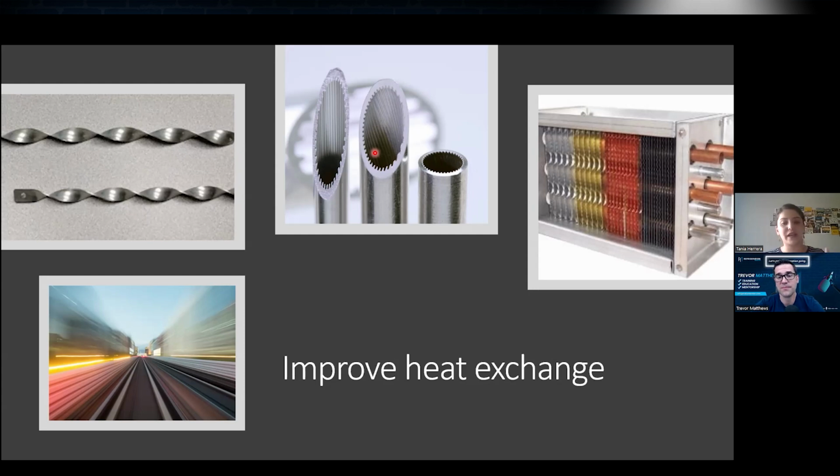For instance, in a condenser, these are very commonly used because in a condenser the inlet is gas and the outlet is liquid, right? But in the middle, we have a mixture of that. So we want the liquid to be flowing through all these mini channels, and the gas flowing through the inside of the piping helps us to have good velocities.